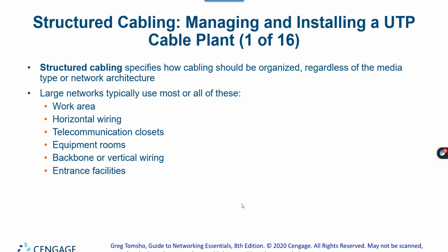One of the things we don't want happening is we don't want to have our power distribution wires, our Molex, our wires that carry voltage next to networking cabling.